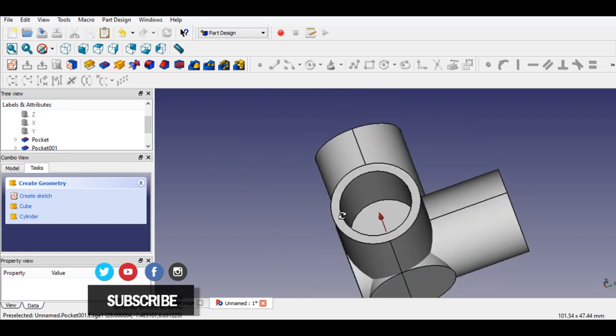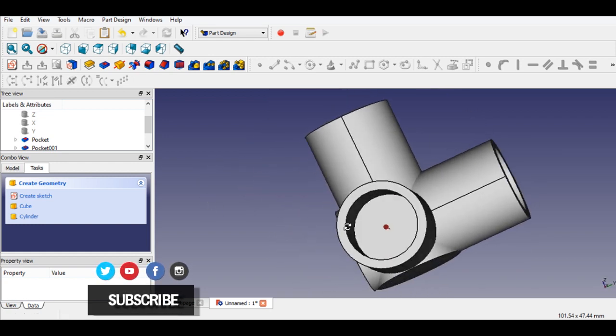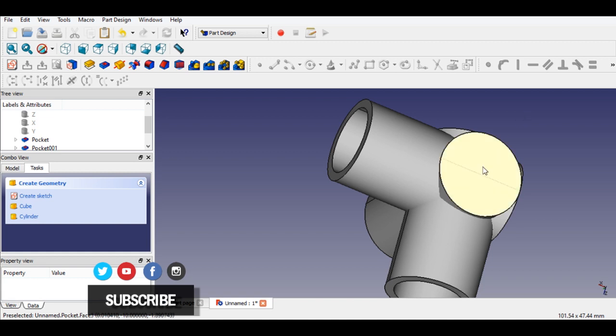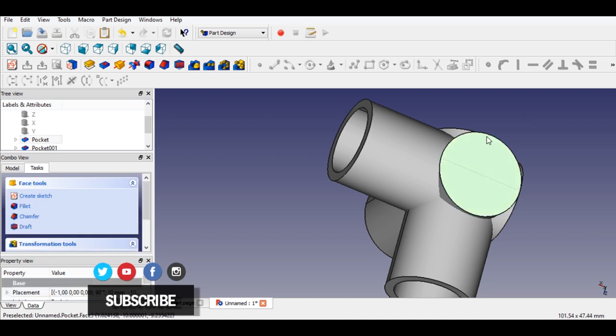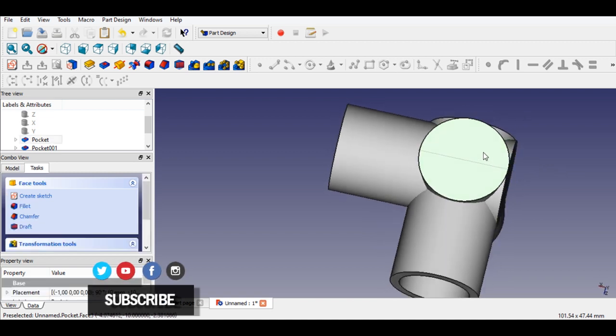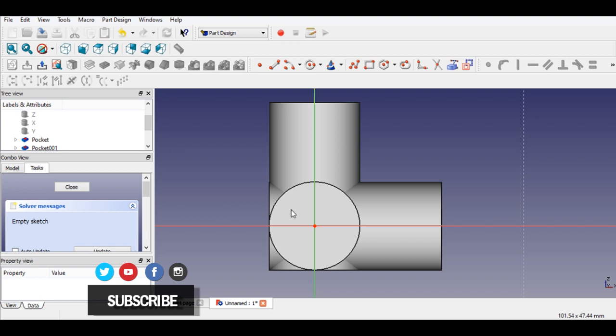There it is. But as we saw before, we still need to make a hole here. I can show you something that will happen, but it's just to show you. And I click on the circle. I click on the middle of the origin. And on the circle. And you go here. What does it say? Create a coincident constraint. Click on that. So you put it in the middle of it.